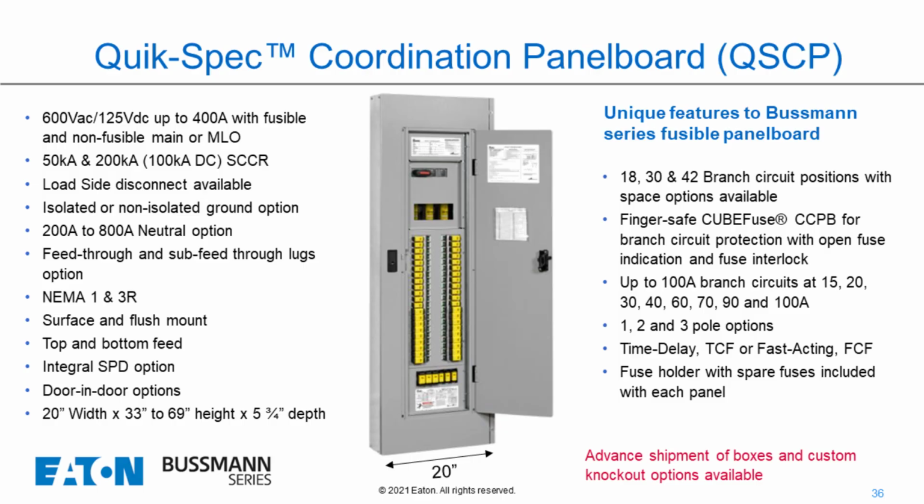And so if you're thinking about it, we're at a lighting panel. When does the fuse ever really go in a lighting panel itself? It's when the ballast shorts out or something happens on the wire, and so on. Are we changing the fuses out all the time? The answer is no, right? But we do have spare fuses. And if you're a design engineer, you design this in, the customer can see that, hey, we can have spare fuses. And if a fuse does open up, he's got spare fuses there to change out the ballast and then put a new fuse in there, right?